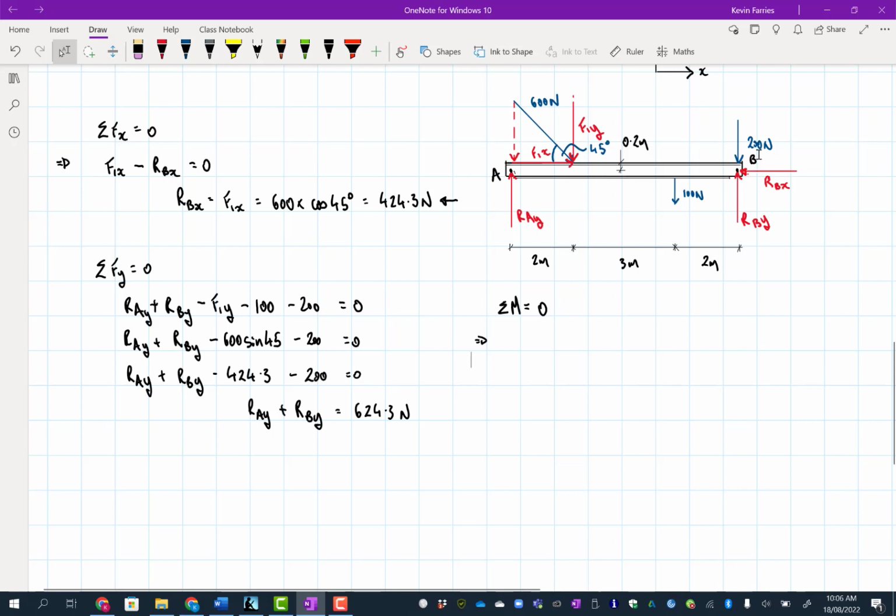But I'm just thinking now, okay, B has 3 forces going to it. So I can eliminate all 3 of those if I take that point. Whereas if I take this point here, there's only 1 force I'm eliminating if I use that moment. All of these other ones all have moments. So it's going to make my calculation easier if I use B, get rid of all these because they've all got 0 moment because they all go through that point. And then I only have to calculate the other ones. So I'll do that now.